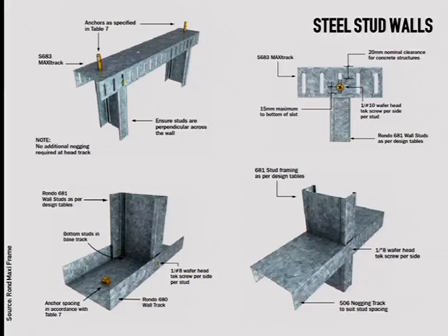And there are a few differences though. So the elements need to be connected, like interlocked together. So in theory, the stud has to be slightly smaller than the track. And also the connections, you see, they've got these slots. So you don't use nails, but you use these slots because the wall tracks can deform, again, due to bending moment. And this slight deformation has to be taken into account by that connection. So this slot actually allows this track to bend, take this type of shape, and translate. Okay, so there is a release. Remember that, it's very important.